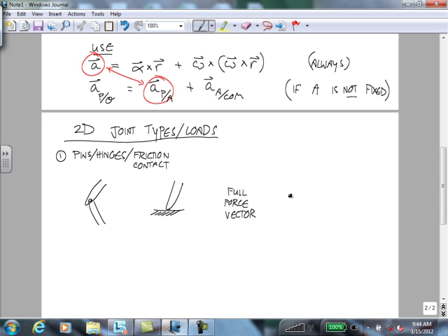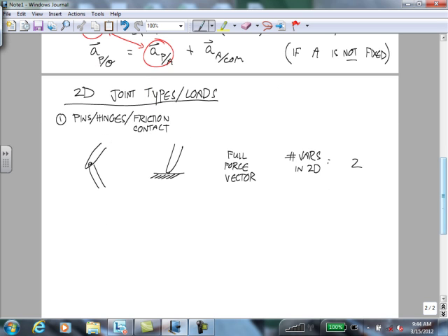There's a roller. There's a pin in a slot. Here's a frictionless contact. Looks just the same as the friction contact, but it'll say that you're assuming that it's frictionless. And so even though these things look the same in drawings and descriptions of problems, you have to treat them differently mathematically.